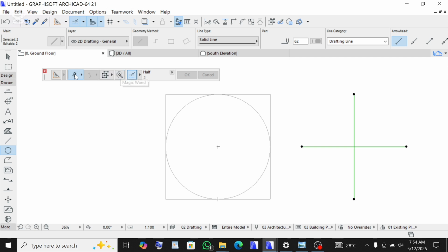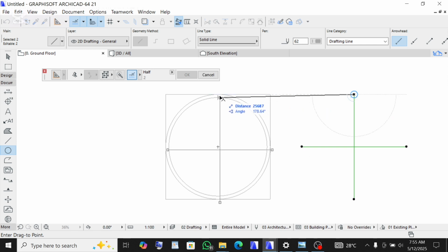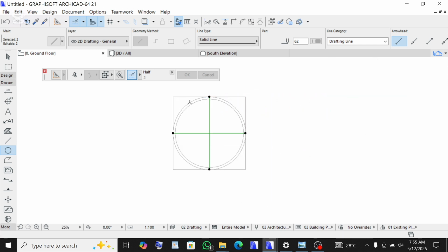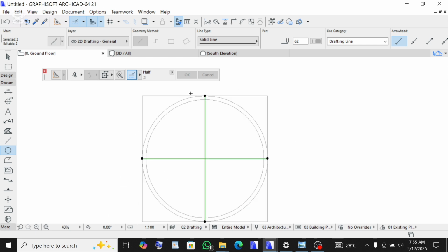Now click back, make sure you have ticked the circular tool and tick this magic wand. Now go in, click on this circular and take it in, then type the offset on the keyboard 600, then press enter. You can see now we can bring this back by pressing Ctrl D simultaneously on the keyboard. Click one node and bring it back like this. Make sure you place it to the same place you took it from, like this.